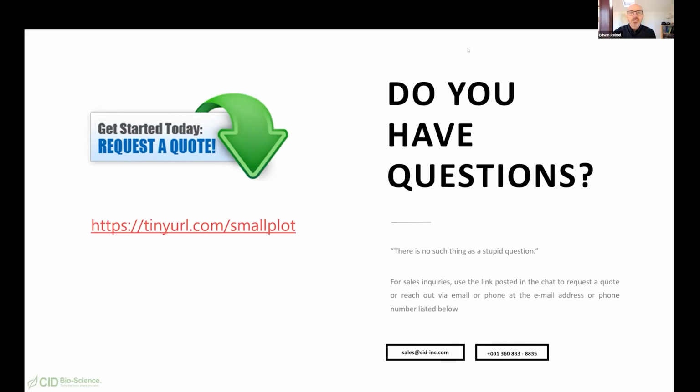Okay, this question from Michael is the topic for another completely separate webinar. So I think it's a bit beyond the scope of what we can do today. General guidelines are that RGB cameras provide higher spatial resolution, and multispectral cameras are generally much lower spatial resolution. So the level of detail does provide some advantages. And the multispectral are narrow band, whereas the RGB is a wide band. So an RGB sensor is a multispectral sensor, and it's just a multispectral sensor that's designed to measure wide bands within the red, green, and blue portions of the visible spectrum. So it's not necessarily a hard and fast distinction between RGB and multispectral.